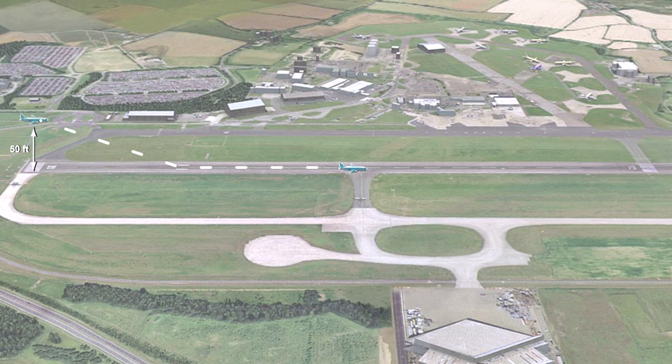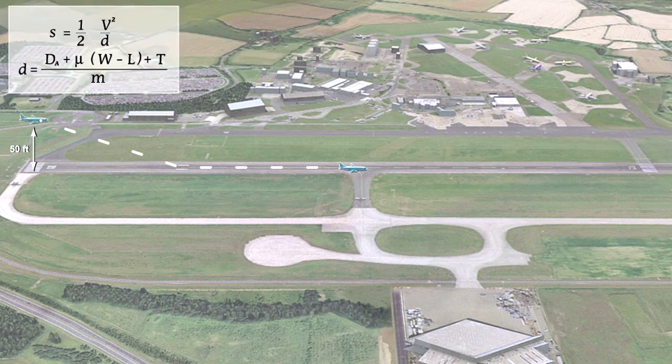Increasing mass has three significant effects on the landing, all of which can be observed in the formula for the landing distance. The first is that a greater amount of mass for a given force applied will reduce the deceleration that the aeroplane can achieve. Essentially, the heavier the object, the harder it is to decelerate it. This is the effect of momentum. More mass will create more momentum. If the deceleration of the aeroplane is reduced, then the landing distance will increase.